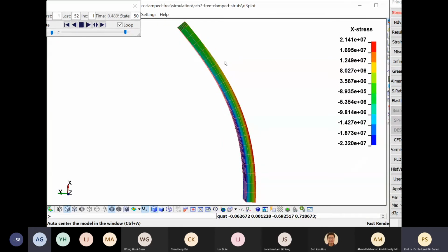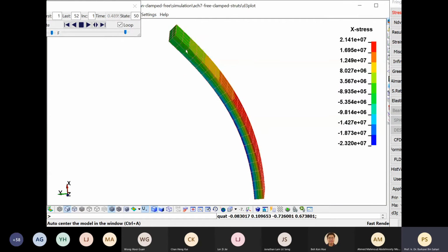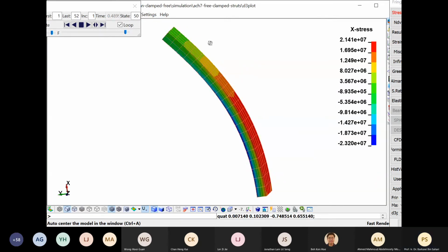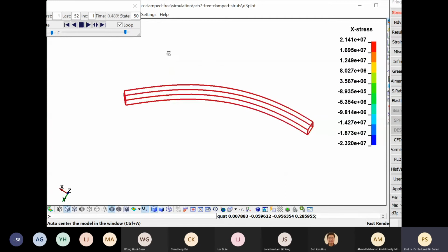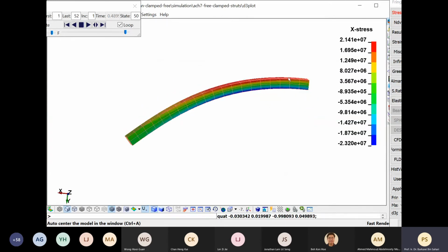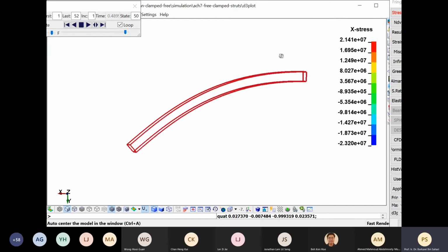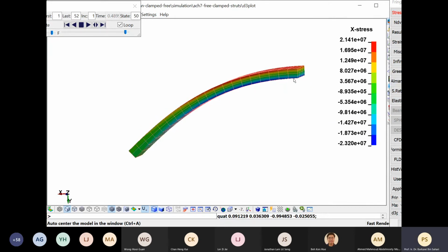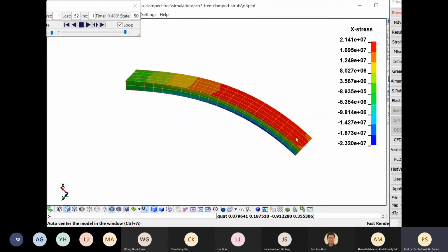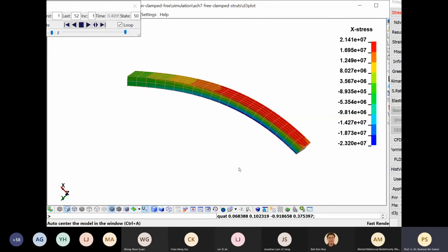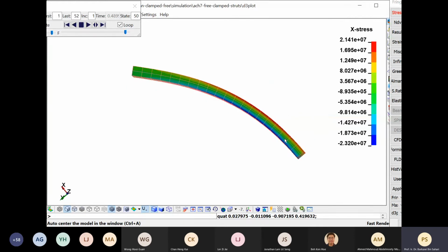Now effective length says that it is the distance between two points on the column where the bending moment is zero. For this case you only have one. So in that sense, what we have to do is to have an imaginary column on the other side of this beam, so the distance will be twice the length of the beam. We'll see that in the lecture notes later on.